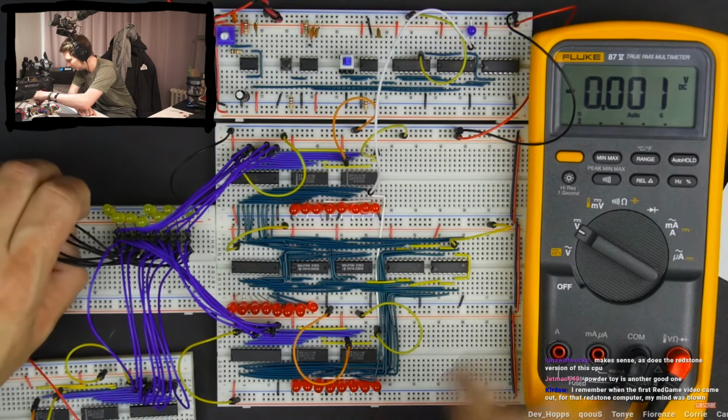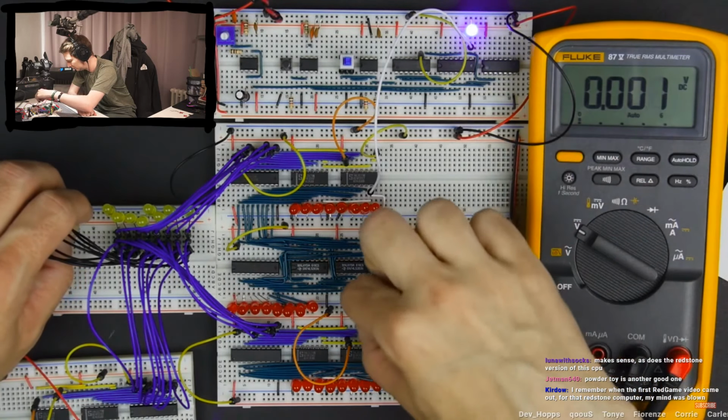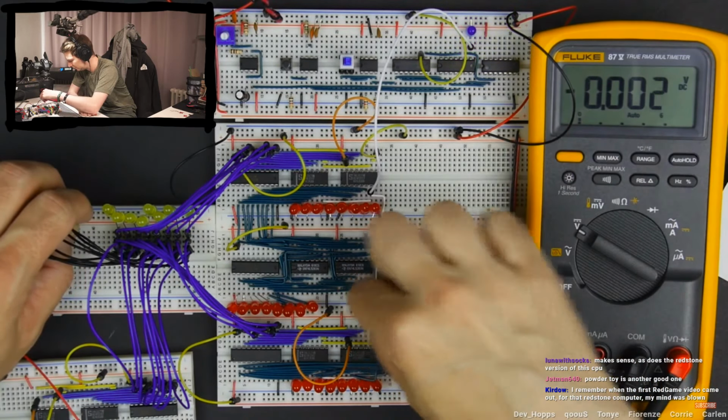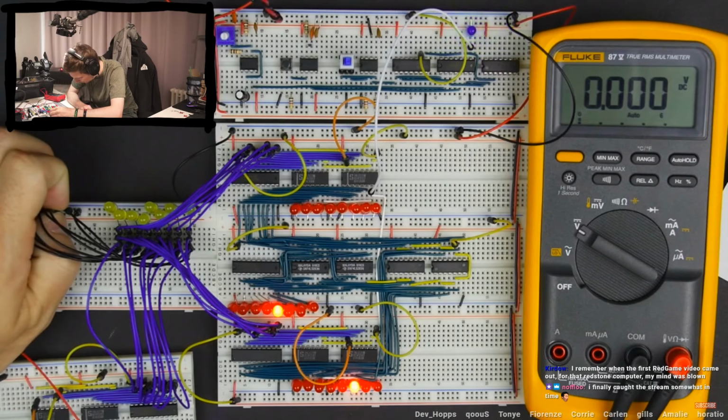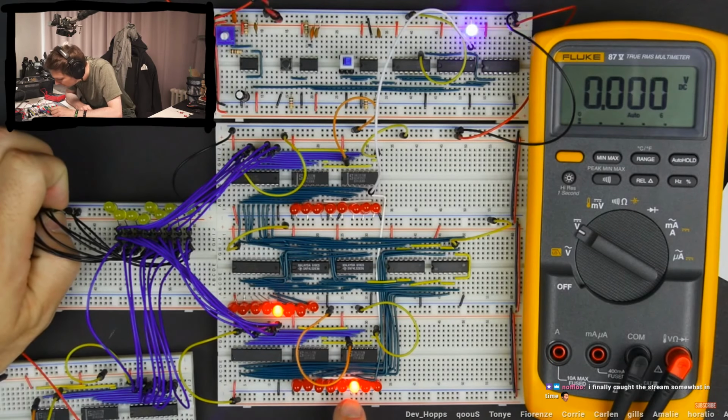Oops, nope, that's our subtract bit. This is the B register load. There we go. So again, now instead of a number plus 0, we're doing 0 plus some number in the B register, and we can see if we can figure out if the B register is hooked up properly. So that's our first bit. Our second bit looks good. Third bit is off, and this is, okay, interesting.